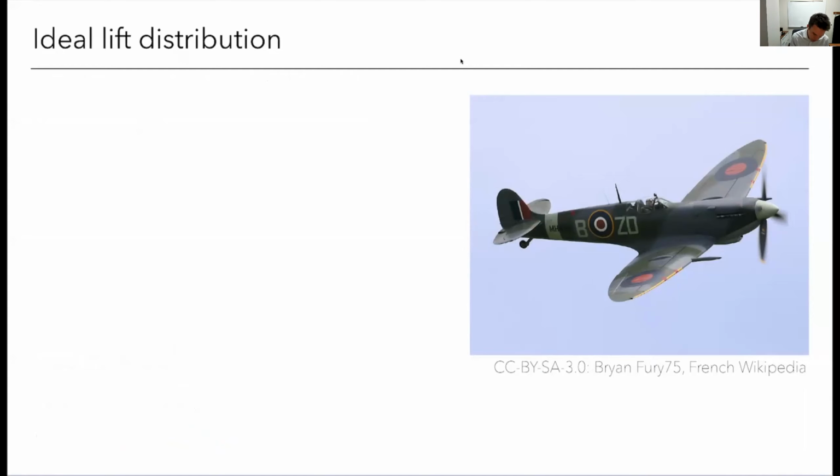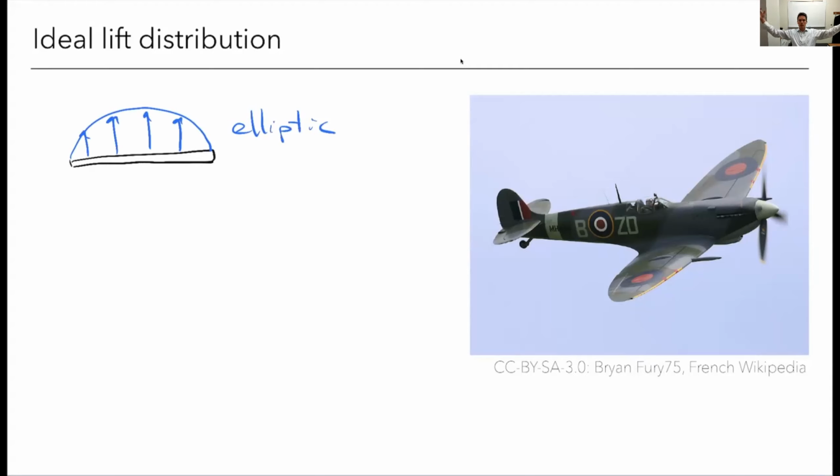If you recall, this is the back view of my wing, it was when the lift distribution looked like this. It was an ellipse. We had an elliptic lift distribution. Okay, so this is elliptic. Meaning if I was to plot those forces that were acting over the wing, they go to 0 at the wingtips, and right at the center, they kind of come up, and that shape, those forces, that distributed load, is an ellipse. That is the minimum induced drag solution for a fixed span and a planar geometry.